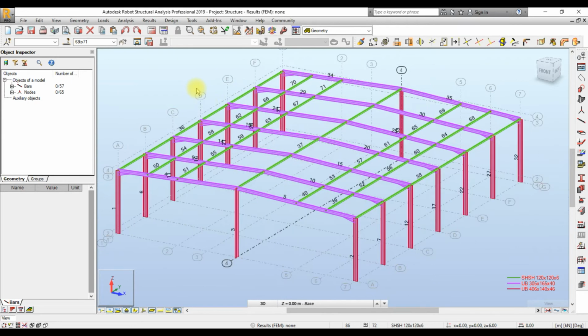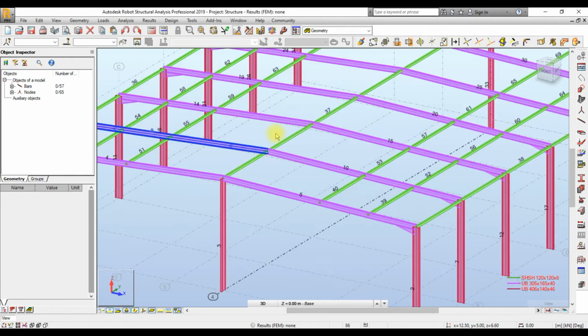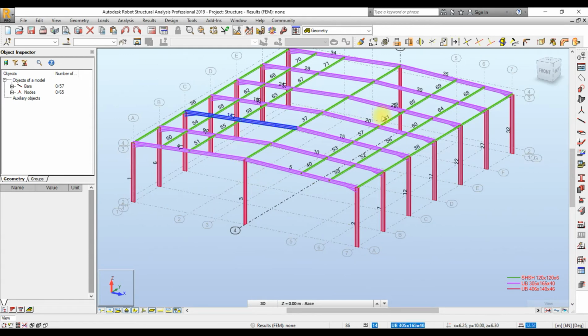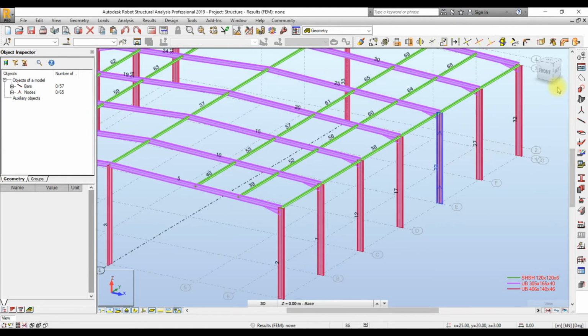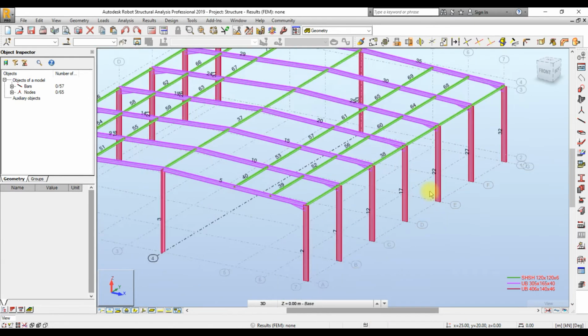So I'll put some bracings. The bracing on the roof, it all depends on you, but for the side here, it depends on what you have on your architectural drawing, so you have to be very careful. If you have an entrance here and you are running an X brace here, you should know that people will have to pass through here.